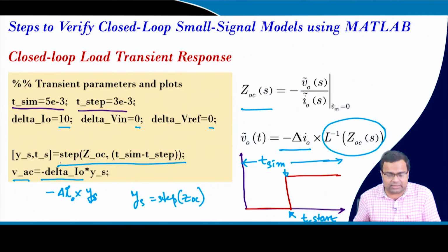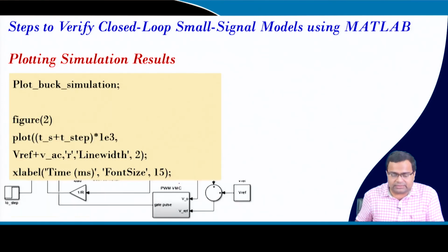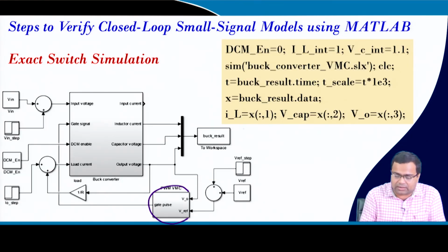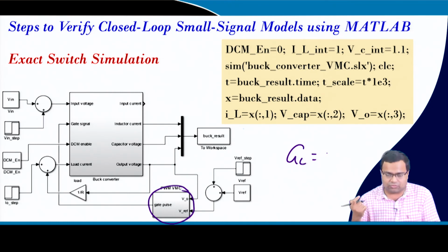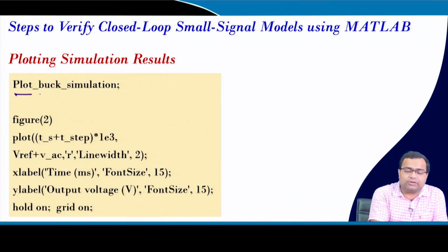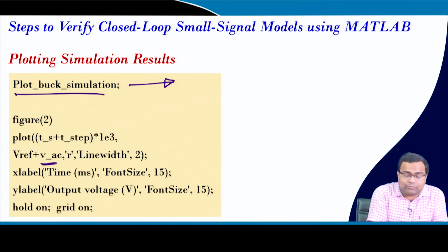switch simulation, right. So, here if we go inside that controller, there will be a controller where we are using coefficient numerator control, denominator control. We will go to that very soon. It is actual switch simulation. Then I will use a plot command, I will show you what this is, and then figure, this is my AC simulation response, transient response of the small signal model, and I am adding the operating point, which is a reference voltage.